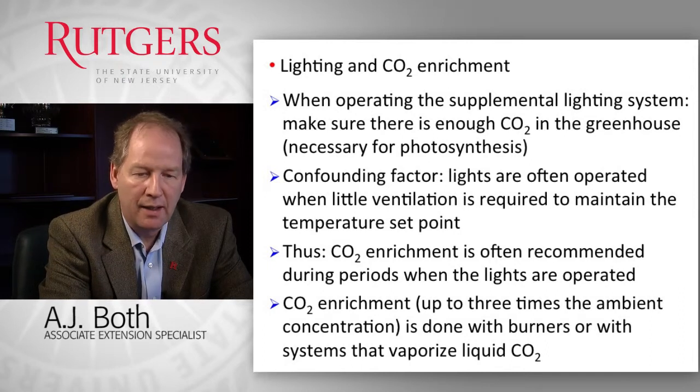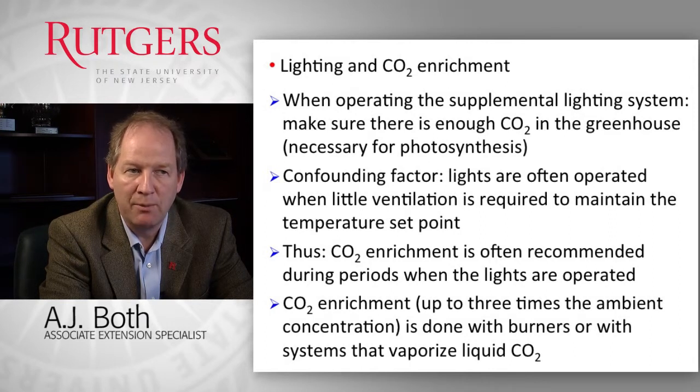When we do lighting, we also want to think about other environmental conditions, and one of the important ones is the carbon dioxide concentration. So if we do lighting, but we don't worry about the carbon dioxide concentration, we run the risk that the carbon dioxide concentration is too low. So we add supplemental lighting, which is expensive, but if the CO2 concentration is not sufficient, we still do not reach the desired plant growth and development.